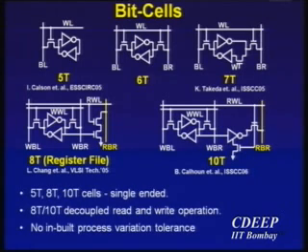The only thing is, if you have a single-ended read, you can optimize the internal cells for write, because traditionally you also get a good amount of write failures. It's still a single-ended thing, and single-ended is not a problem actually. In an array, the only problem is that it's sometimes difficult to interleave, and the reason interleaving is done is because of soft errors. So it's sometimes difficult to interleave, and there are other problems.